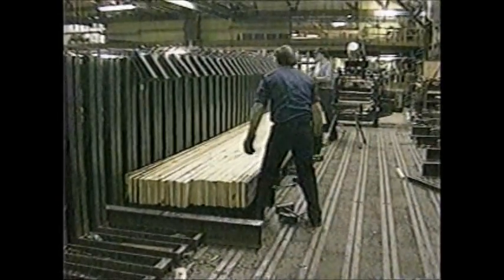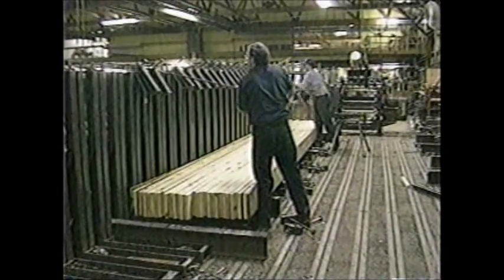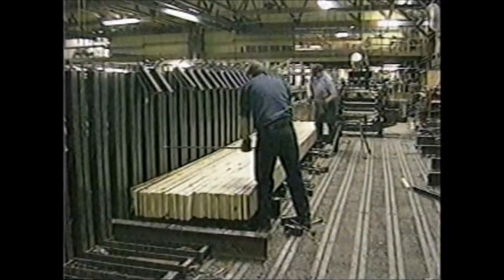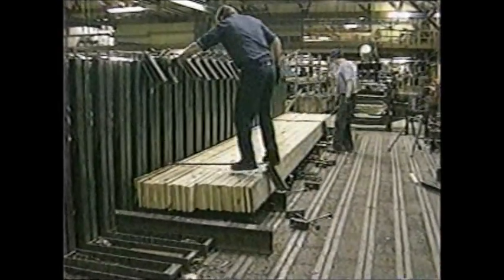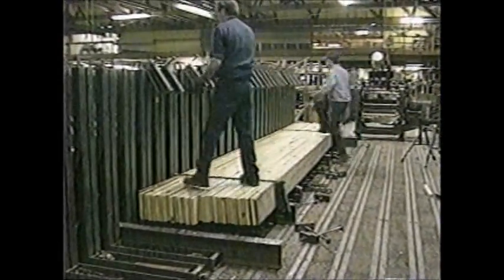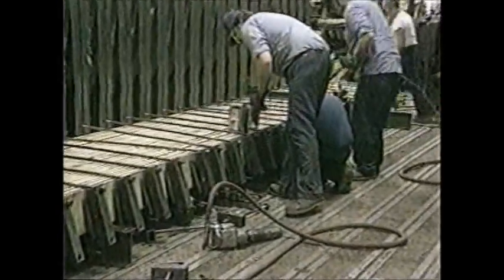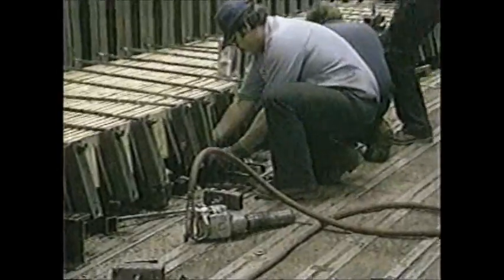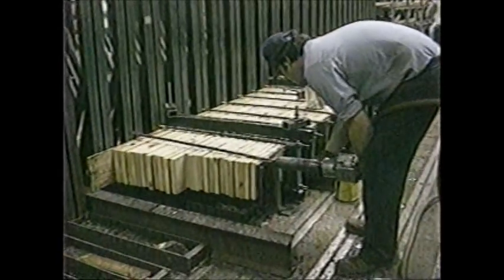After the laminations have been glued and assembled, clamps are assembled and carefully tightened. The assembly is clamped to ensure that the laminations are stacked correctly and that the glue joints are held under pressure.